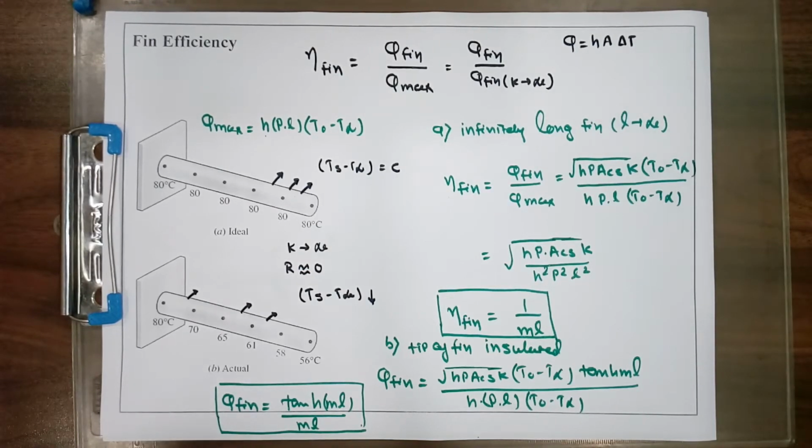But beyond certain limits of the length we cannot justify the effectiveness or the efficiency of the length, so for that we need to go for various geometries. If we discuss geometries like triangular and parabolic, the perimeter of this kind of geometry is very high compared to the other geometries. So the design of fin is considered on two parameters based on the efficiency of fin, that is perimeter and length.